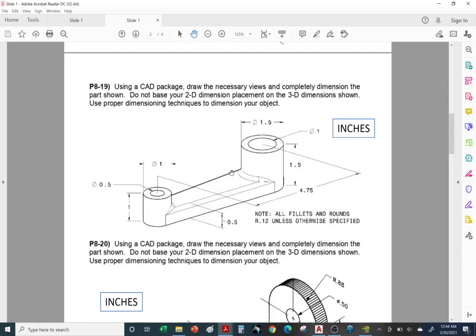Let's say it can be half an inch and it'll have its half-inch dimension. Its radius of half inch, for example. But since these don't have any dimensions, here it is. We follow this note, and again, this is a very common note as used on drawings. We try and avoid using symbols, but this is one of the few exceptions. Or I should say we avoid trying to use letters and instead use symbols. So this is one of the exceptions.